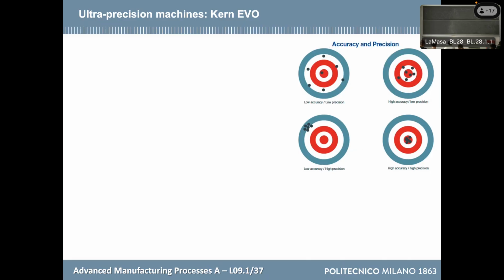So, for example, I want to verify a tolerance of 0.1, 1/10 of millimeter. It is better if my machine has an uncertainty of 1/100th of millimeter, 0.01. It is a rule of thumb, but it works, and it is also applied in practice. So, for example, that optical machine has a micron level precision. So if I want to measure something of 10 microns, I'm safe with that machine, and I can consider it as perfect. I measure my dimension and I see that I have a distance.